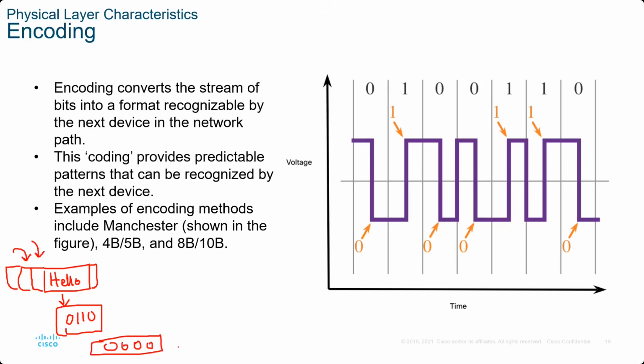That's totally possible. Or it turns into 1, 1, 1, which is totally possible. Now, if you start transmitting 0, 0, 0s or 1, 1, 1, 1, it starts causing troubles in the transmission on the other end because you lose synchronization, because your bits are not changing at all. If there is no change, that means you're not sending any information, and the other end actually has problems in receiving this sort of sequence of bits which are always the same. It loses the timing. It cannot see where the bit starts and where it ends, and it starts drifting.